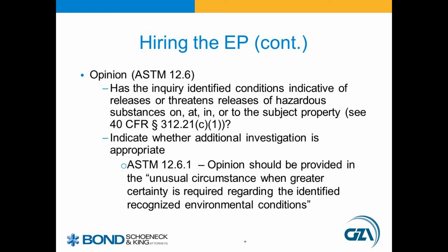The environmental professional's opinion is the root of the Phase 1 report. Has the AAI inquiry identified conditions indicative of releases or threatened releases of hazardous substances on, at, in, or to the subject property? The EP's opinion of if and how RECs may have impacted the property will include their logic and rationale for including or excluding a condition as a REC. RECs are subsequently summarized in the summary section of the report.